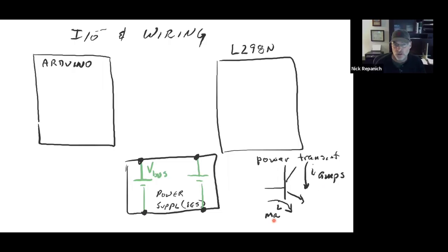So there's two circuits you've got to run to make this thing work. One is probably 5 volts to turn on and off the transistor. Well, you're not going to do that with that. So you're going to need a power supply for that circuit. You're going to need a different power supply for that circuit, for the amps, right? So it's getting a little complicated.